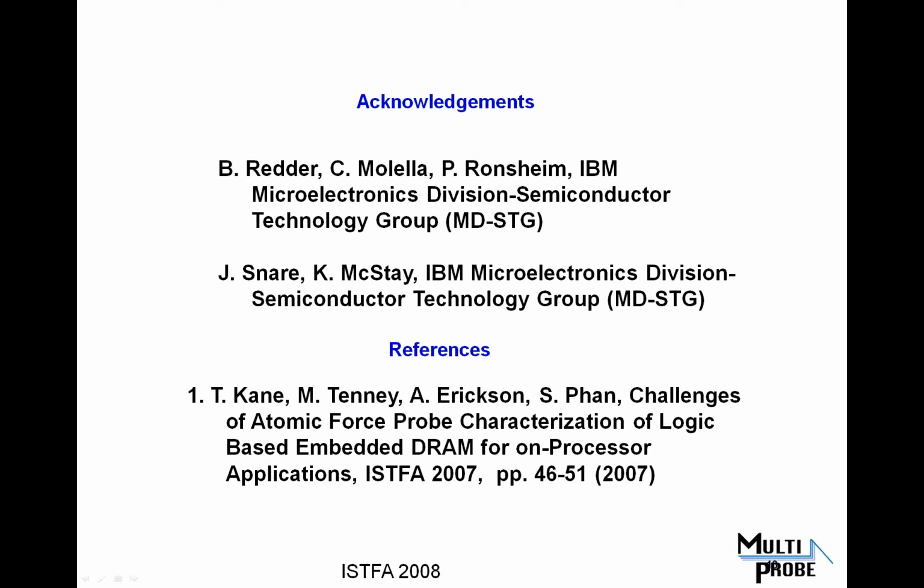Yeah, in typical SOI SRAM cells, there's no body tie. Right? So I just don't know how to decouple those components. Well, like I said, I think you can also use the connection. There's still a connection to the box layer. It doesn't matter that there's an isolator in between. That's just another capacitance in the series. And to my understanding, depending upon how many devices are into the body or the well that's there, those are often longer structures, and so they would have significant capacitance. And then it would just be a correction to that number.